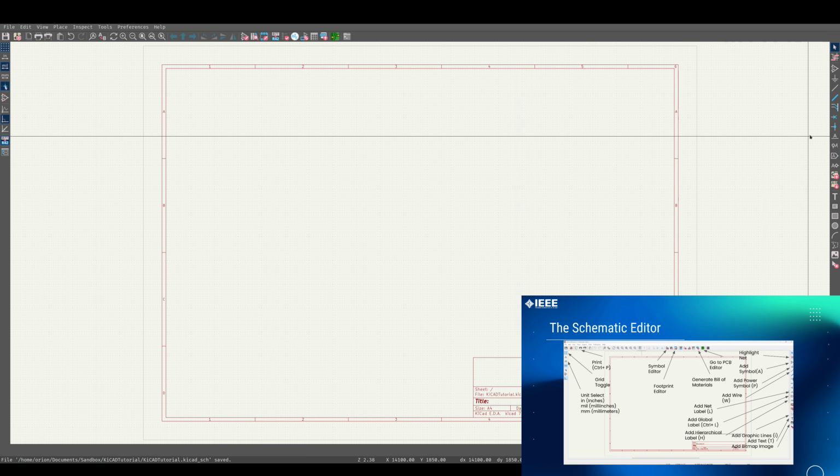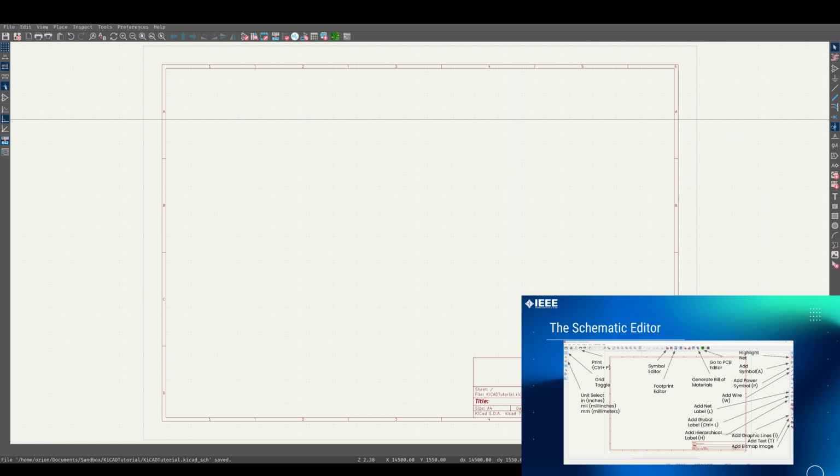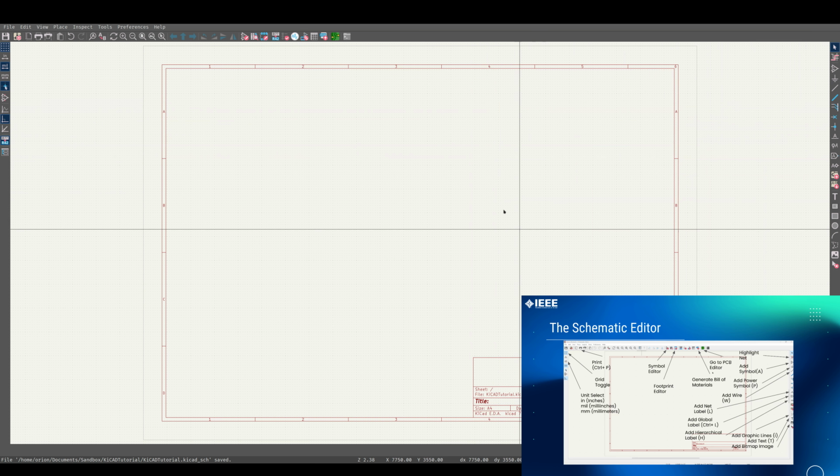Basically indicates that you don't want to connect that pin to anything. Junction adds a connection point between 2 lines that are going in different directions. Label adds just a label to it. I'll be going over that later. Net class directive, we don't need to cover that.